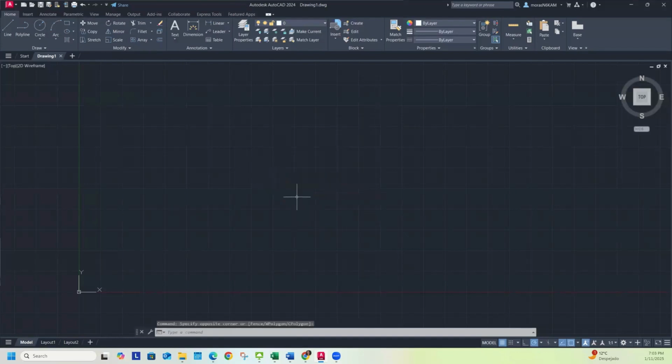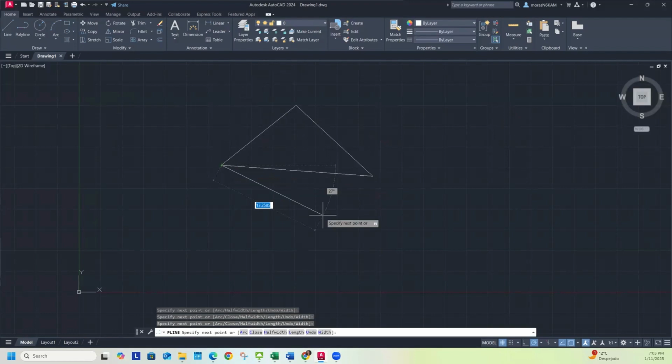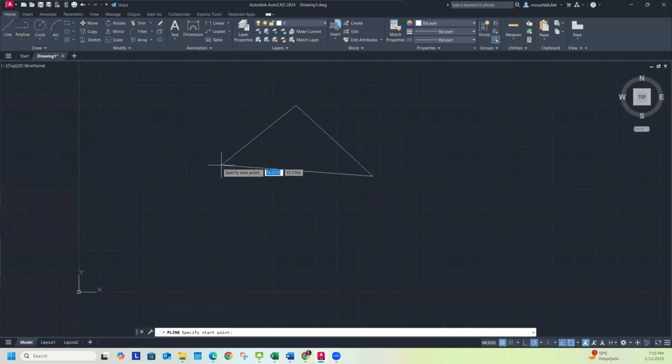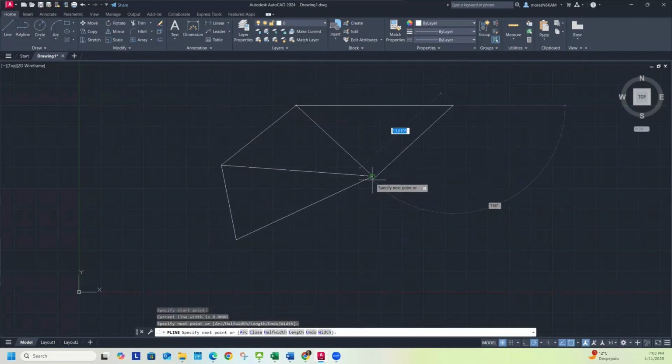And so here I have AutoCAD open. If I do the command PL, I'm now in my polyline command tool, right? And then polyline can also be found here in the drawing panel, but it's not as fast for me to go up here every time I want to use it. And then I can escape, and then I go back up here when I want to use it again. Instead, I can just do PL, and then I can use it that way.